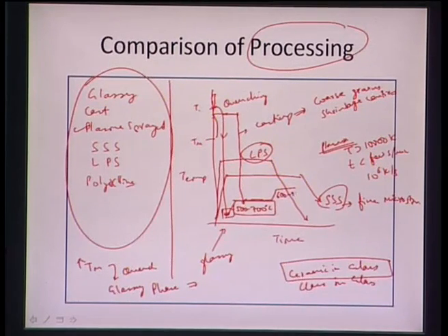So at 600 to 900 degrees centigrade, we can let the nuclei grow at much higher temperatures. And then if we let it cool down, what we have gotten is ceramic in glass, because the overall matrix can still be glassy depending on the way we cool it, but most of the nucleus is already formed. If the nucleus formed completely, we can get a polycrystalline matrix, and so we get all the grains which are very fine, and everything is much more crystalline or ceramic. But it can again be glass in glass.